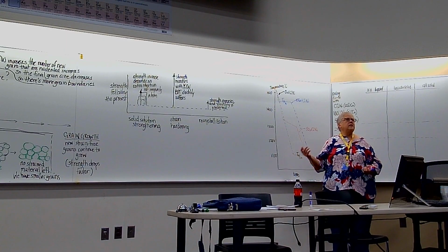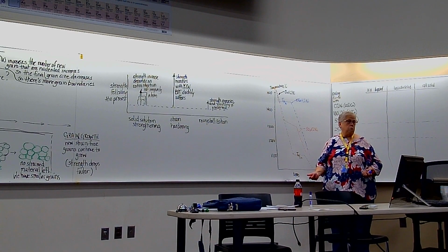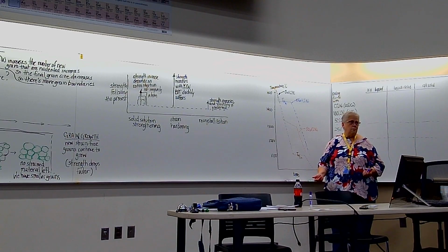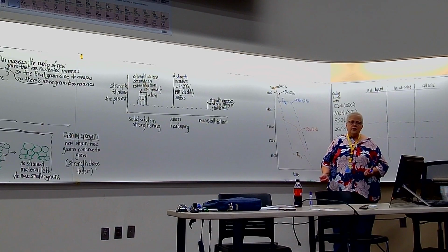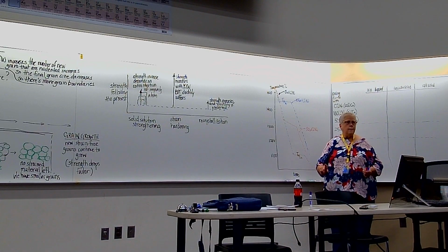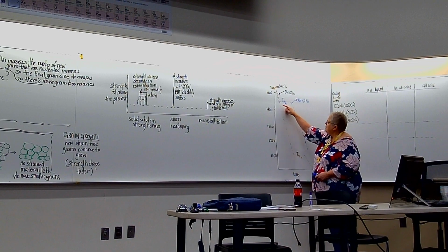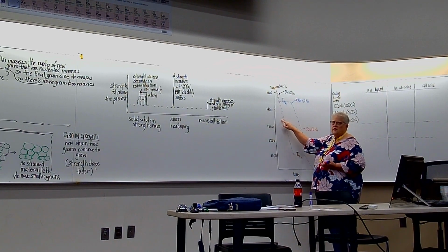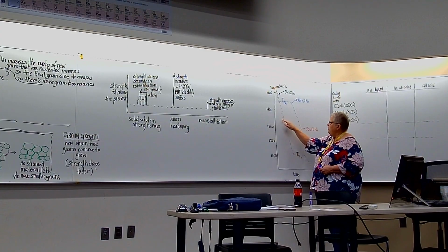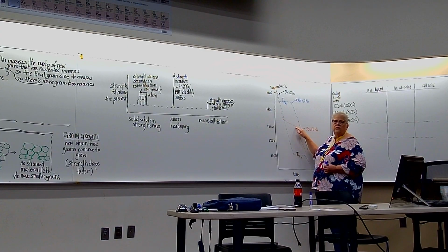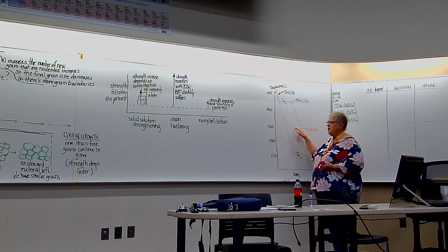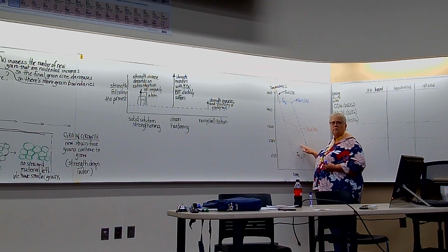Well, what would be the melting temperature then of 50/50? Well, it's 50/50, so it doesn't have one distinct melting temperature. If I have a 50% nickel, 50% copper liquid, and I cool it, I'll get to about 1350 or so, and then this will just change slope until I get down to right around 1300, and then this will just change slope again.